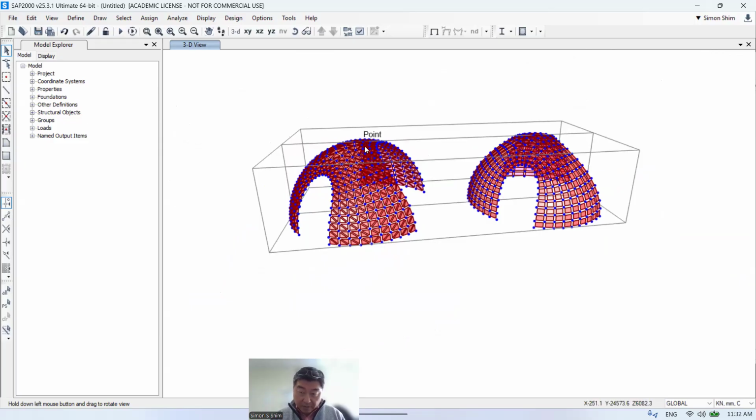So first of all, same thing: it's only geometry. This is a surface. So we need to input material properties, member properties, boundary conditions and loading conditions, right? They're all the same. The input we need to define so that SAP structural analysis software can analyze its static behavior.